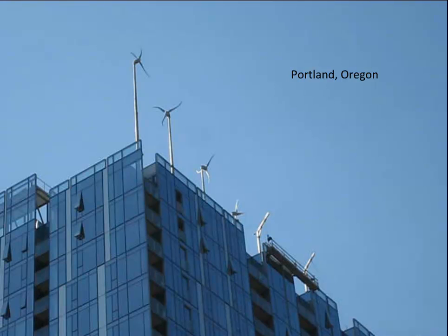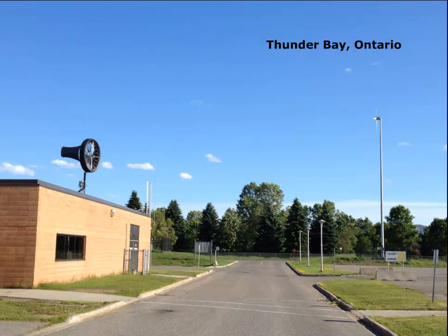Here's some that were in Portland, Oregon. Again, here's just a little evidence that the winds are turbulent: 3 of these 4 were spinning, and they're facing 3 different directions. The turbulent winds are not helping them at all. I took all of these pictures. Here's one in Thunder Bay, Ontario. I took this past summer. And again, I'm not criticizing any turbines as much as I am the siting. Here you've got a turbine that is low to the ground, next to a building. Likely it's not going to produce a lot. The other thing I know is that it's only about 4 foot across. It's not very big. So the reality is it really can't produce a lot of power.